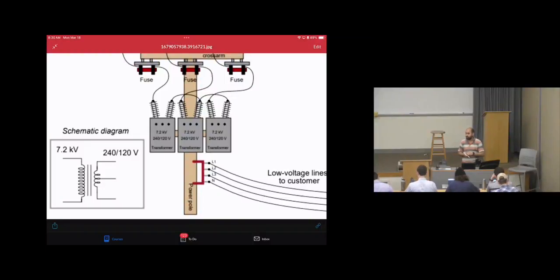How can we avoid this? On a large scale, they try to supply an equal amount of loads to each phase. For a specific neighborhood, for phase A we connect 10 homes, phase B 10 homes, phase C 10 homes. Then the overall average of phase A will be the same as the overall average of phase B and of phase C. So we work based on the average power that they consume.